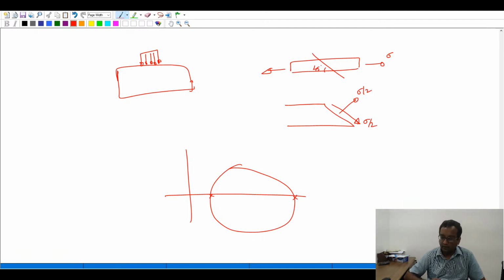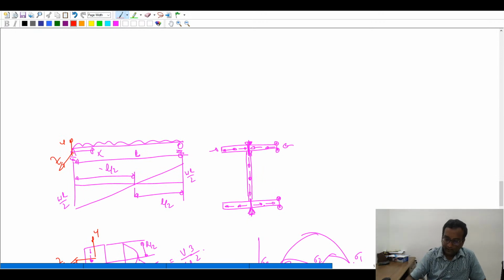Usually on a surface, if you are not applying any forces, the shear stresses are 0. That's the reason why I said these points should have 0 shear stresses, right? Even this surface will have a 0 shear stress, because unless you apply a shear stress, the surface is free of traction, and hence the outside wall will have zero shear stresses.